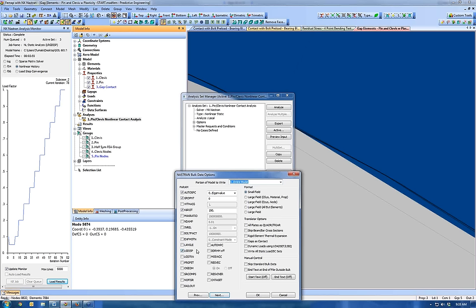So you need large displacement turned on, but at the same time, you don't want to experience large displacements between your contacting bodies. I think that makes sense. I hope that makes sense.